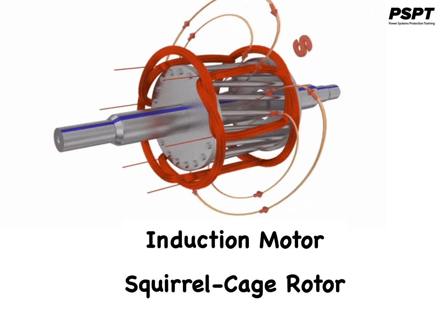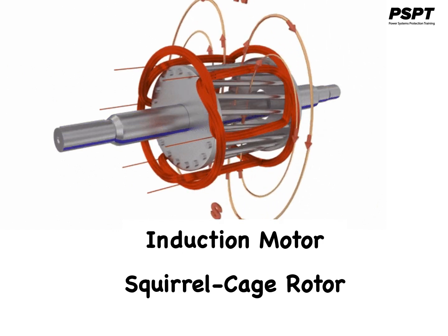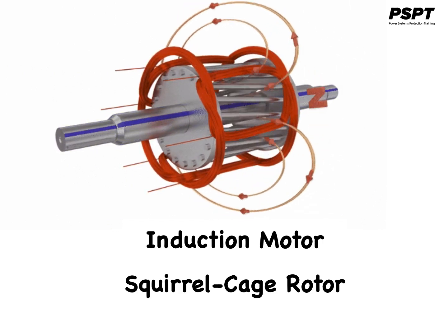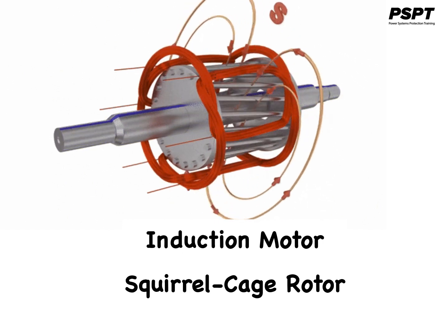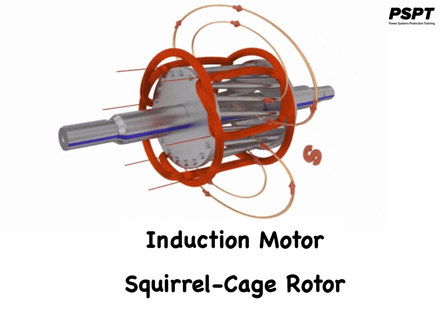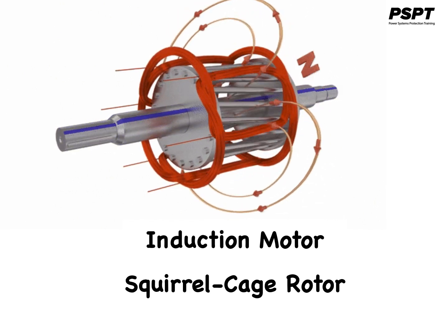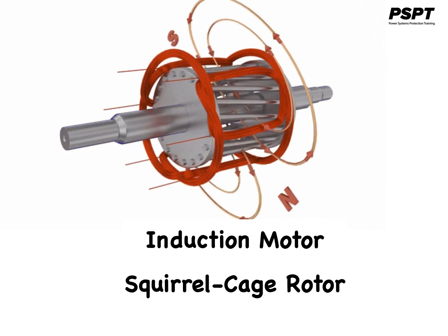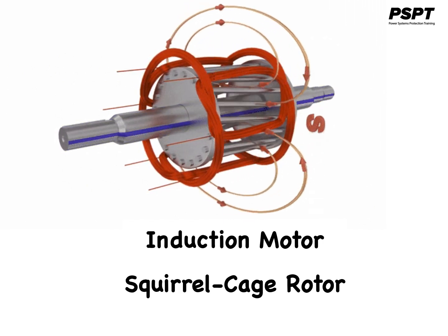When resistance is added to the rotor circuit, the rotor power factor is improved, which results in improved starting torque. This, of course, increases the rotor impedance and therefore decreases the value of the rotor current, but the effect of improved power factor predominates and the starting torque is increased.